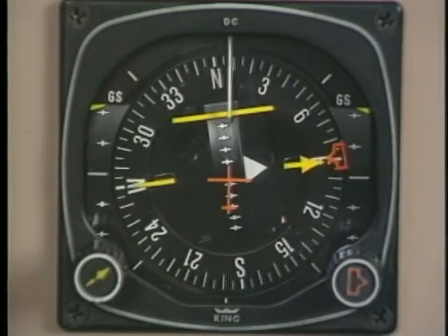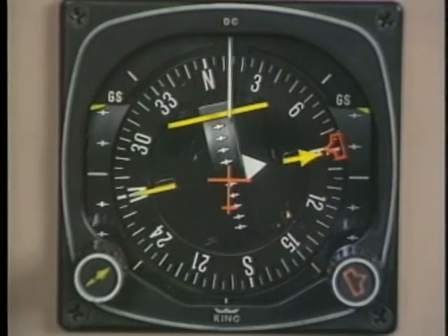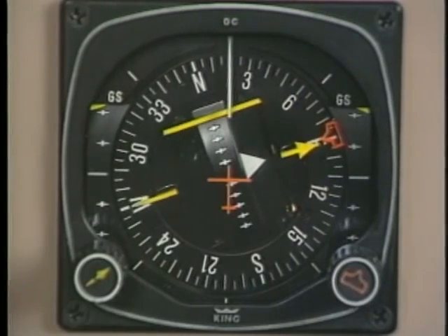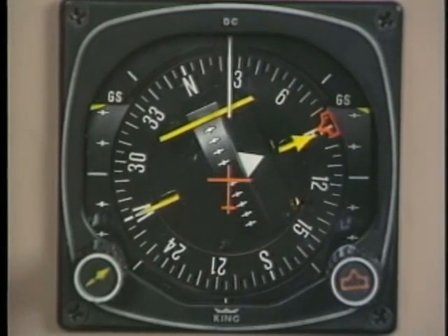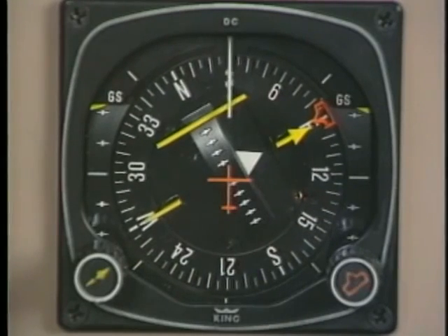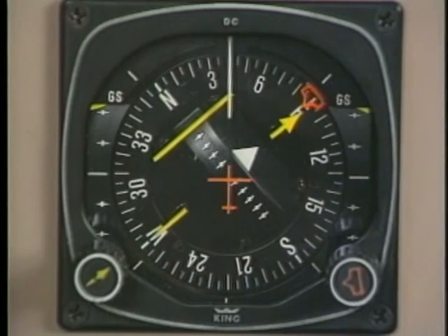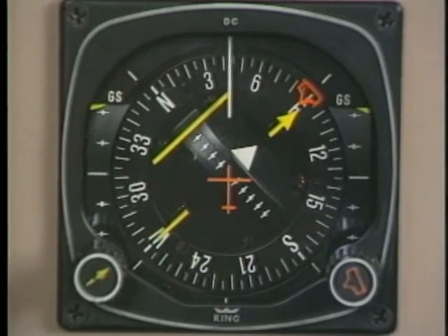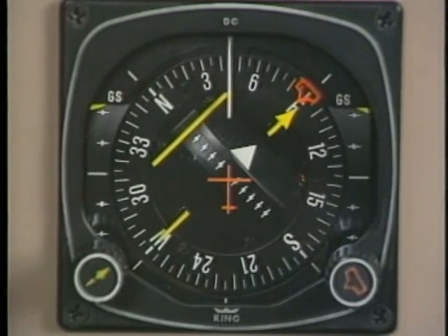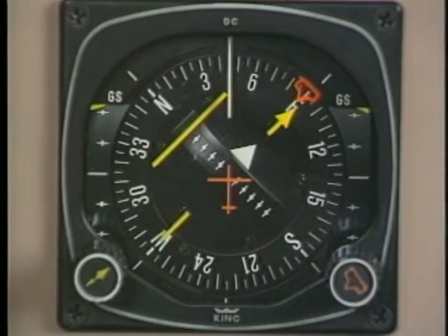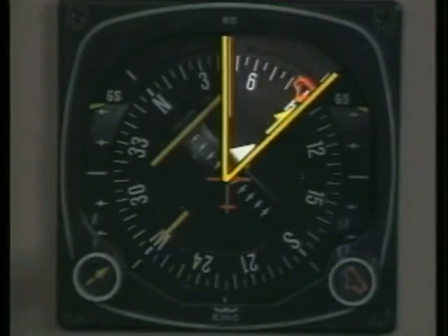You know that you're flying toward the radial at a 90-degree angle. Choosing an intercept angle is simple with an HSI since it provides a visual presentation of your aircraft heading and your selected course. Let's assume you want a 45-degree intercept. After turning the airplane to 045 degrees, notice how the instrument shows your angle as well as your new heading.